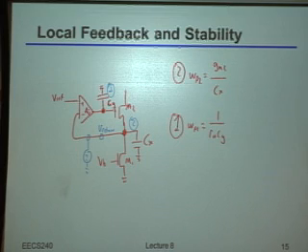Okay? Because if you think about it, if they're less than the gain, that means you're going to cross over while you have a very substantial effect from the second pole coming in and changing your phase margin. Okay?